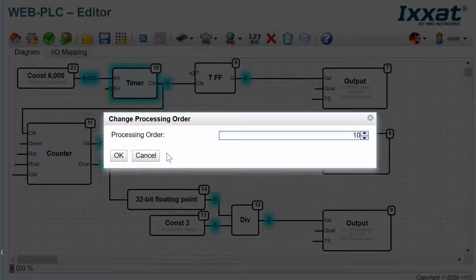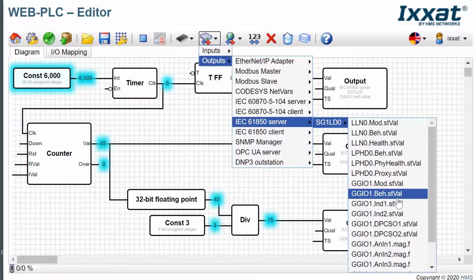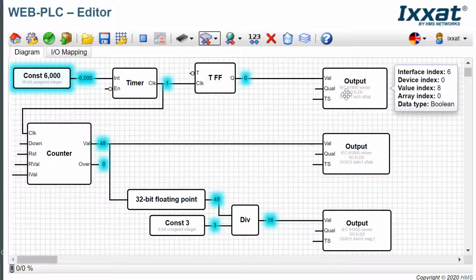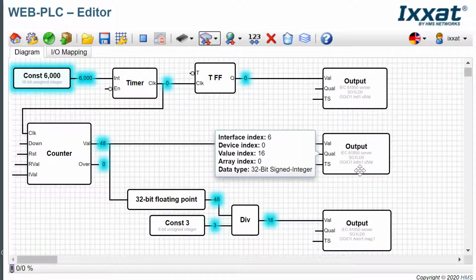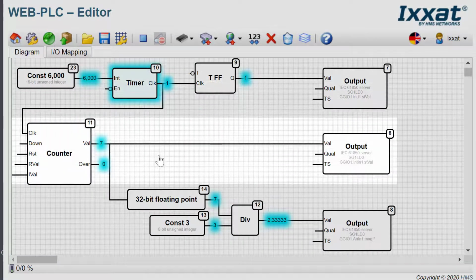That's it so far. Next I will show you 4 types of typical helpful data generators that are valuable testing tools. What kind of data change events are mostly needed? First, the easiest might be to toggle a Boolean data point. Second, for integers a counting value can be very useful.